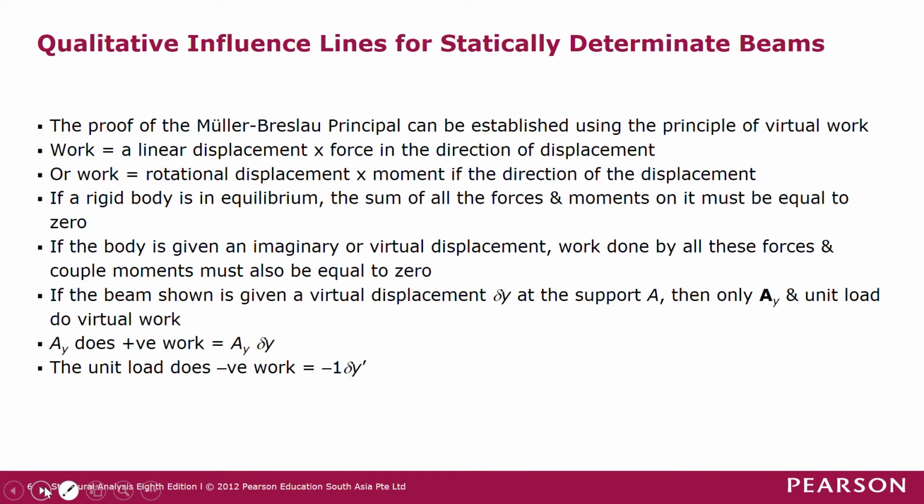So to prove the previously explained method, the proof of the Muller-Breslau principle can be established using the principle of virtual work. Before that, we need to know what work is. Work is a linear displacement times the force in the direction of displacement. This is work done by a force. If the work is done by a moment, then the work is the rotational displacement multiplied by the moment in the direction of the displacement.